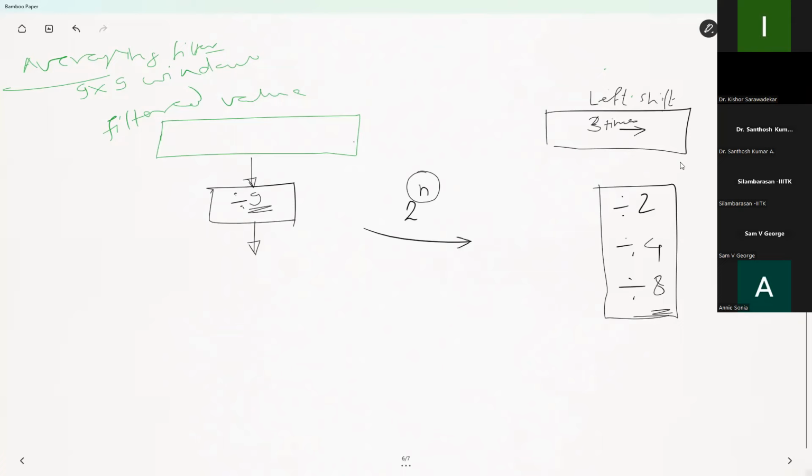So the output obtained immediately after divide by 8 may give the same result for inferences as divide by 9. If that is the case, then forget about divide by 9 and get the job done with divide by 8, so that your hardware resource requirement will reduce and the speed of operation will also be high because it is a shift register.